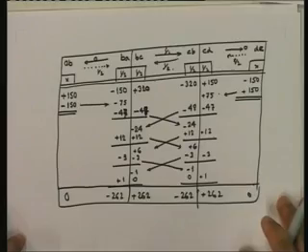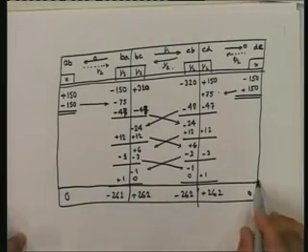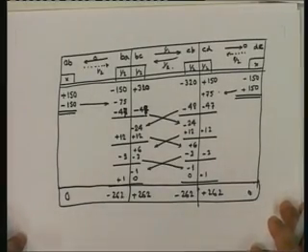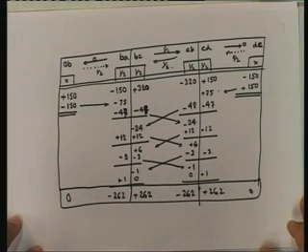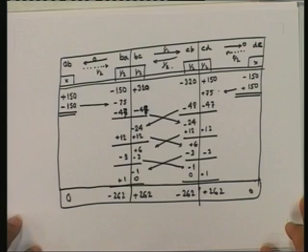Now, once you have this, you've got the member end moments. You can do the distribution. Now, the point that I'm trying to make over here is that I did this problem just to show you that in reality, you don't release one, then clamp the other one.